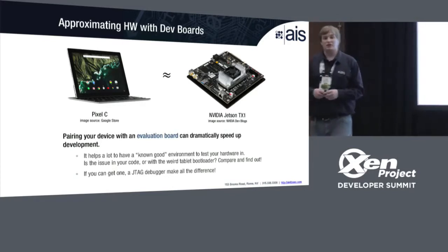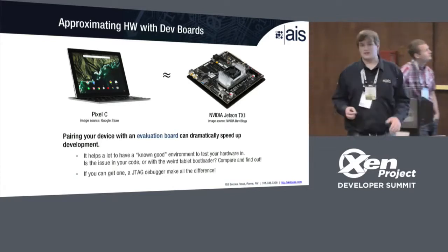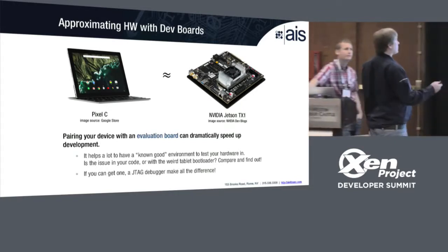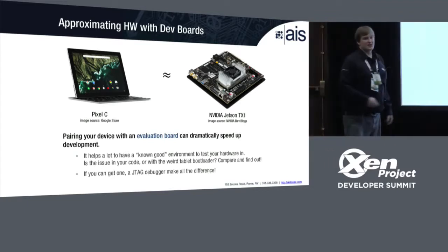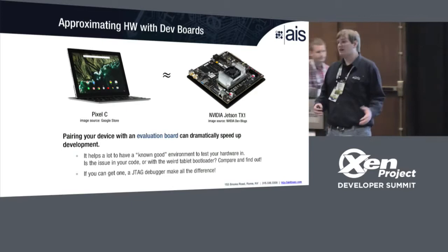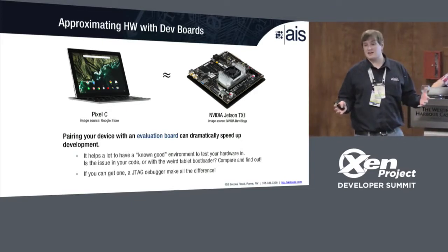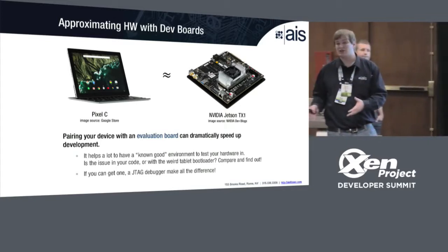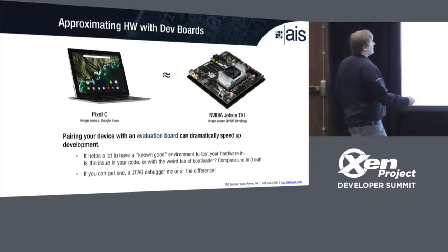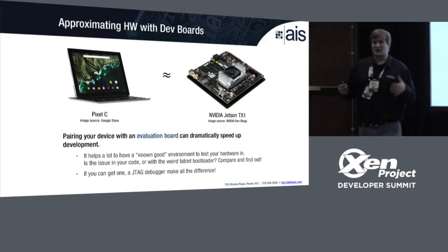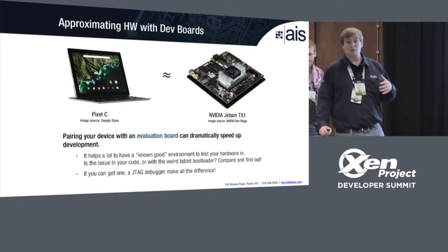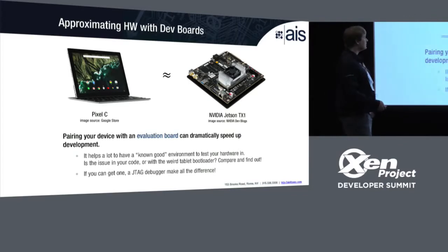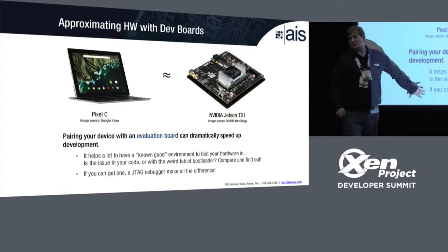Then if you can approximate your tablet with a development board, that is definitely a blessing. Usually they bring out things like JTAGs, stuff that makes it a lot easier to work with, and you don't have to worry about the environmental differences between your tablet and an environment that's friendly to Xen. Right, a lot of these tablets have custom bootloaders that are not present on the evaluation versions. So if you can test on the evaluation board, that's going to give you a nice clean environment where the bootloader is more likely to be transparent and friendly, where you can test your initial experimentation. Right? And again, JTAG is just such a wonderful thing if you can get it.